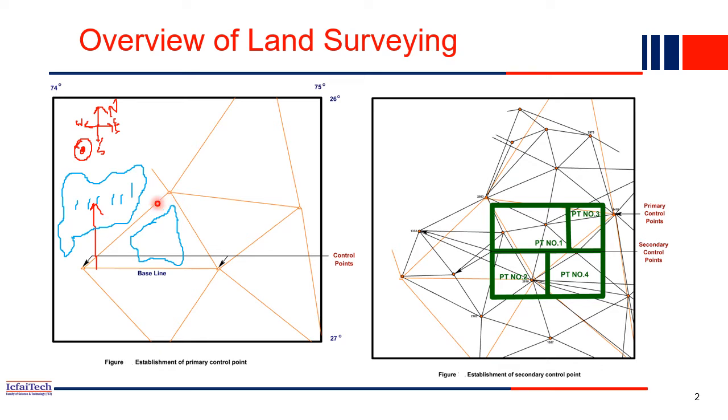So that's why the calculated parameters we have calculated can be further adjusted by satisfying the geometric conditions associated with this triangle, with the figure. Like that, even if we make errors, we can rectify them. Basically this helps in the minimization of errors which will occur during the survey.